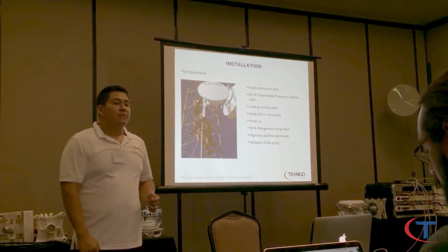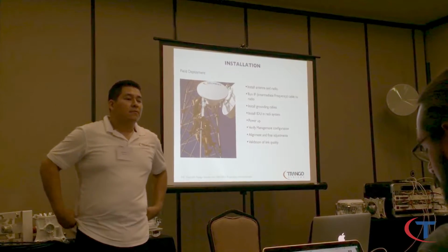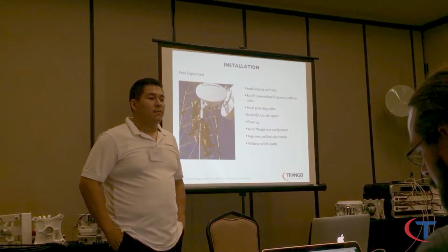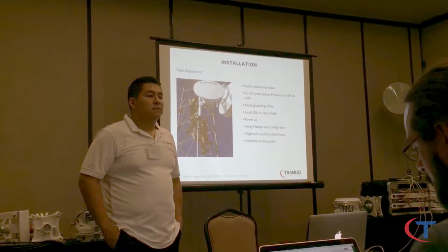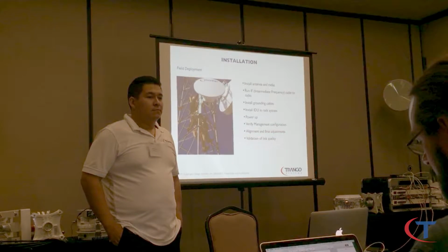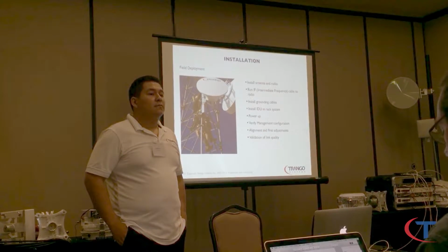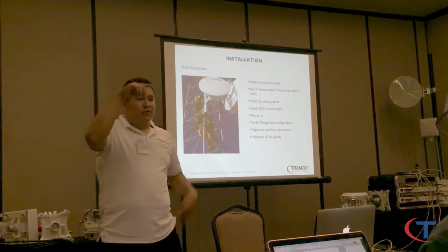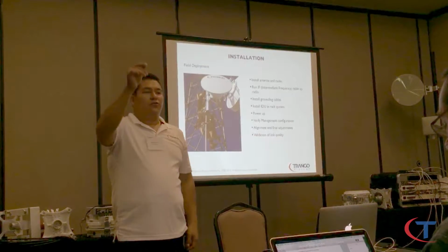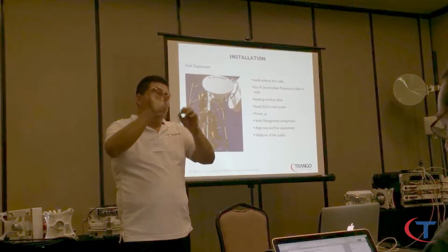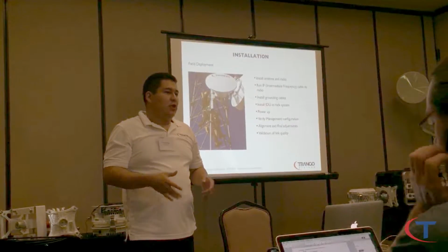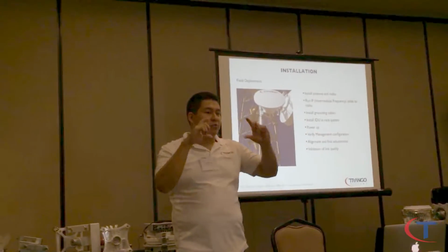On the grounding, we're not going to actually ground the antenna. We're going to ground on the radio, there's a ground on the radio. The ODU, yes. On the ODU, we're going to put a ground from there, and we're going to run that all the way down the tower. No, you can actually ground it at the tower. So it's going to be literally the ODU, and then you ground your green cable, basically your thick cable, to the actual structure, which is grounded itself. So you have to run it all the way down, just to the grounding block there.